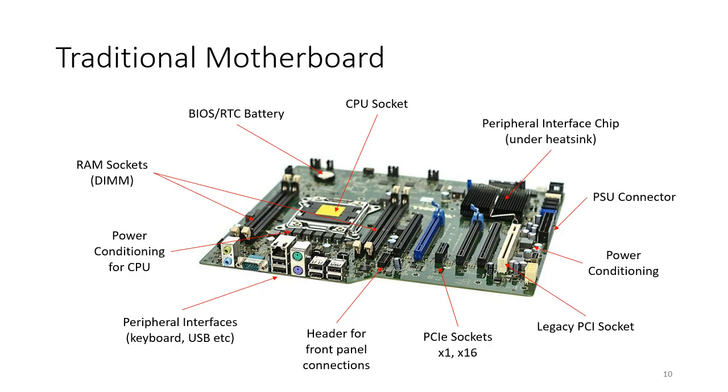Now in this particular motherboard, we now have multiple PCIe slots. So there's full-length PCIe, which might be used for some peripherals. There's one there, you see the blue one, and not the next one immediately, but moving to the right, there's another one which has got those connectors on. They're probably used for graphics cards. Graphics cards use a higher speed version of PCIe.